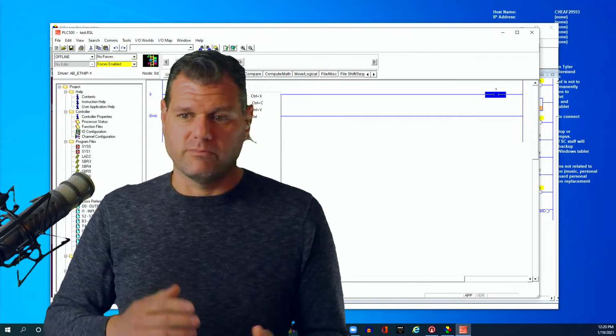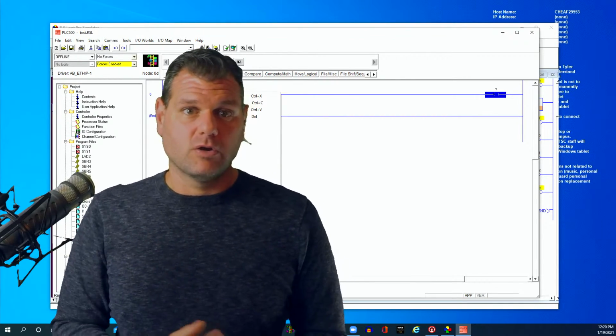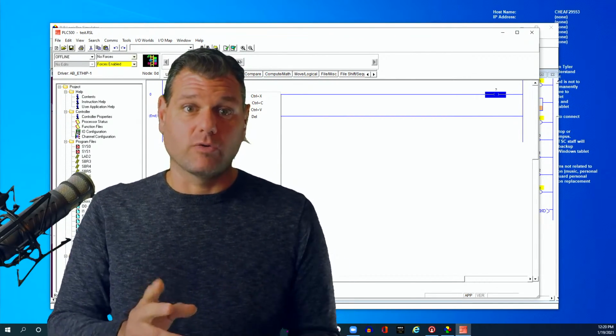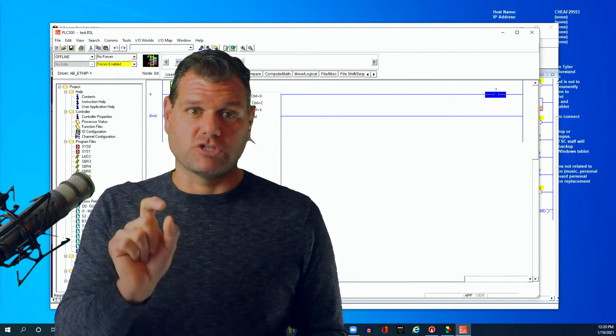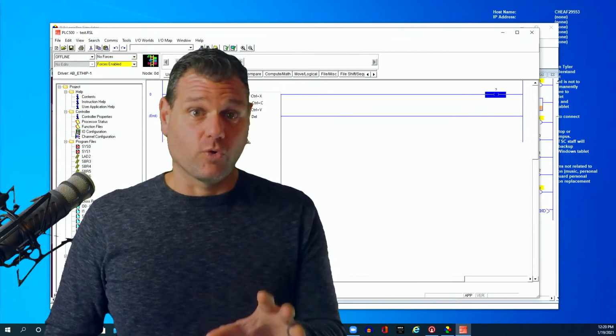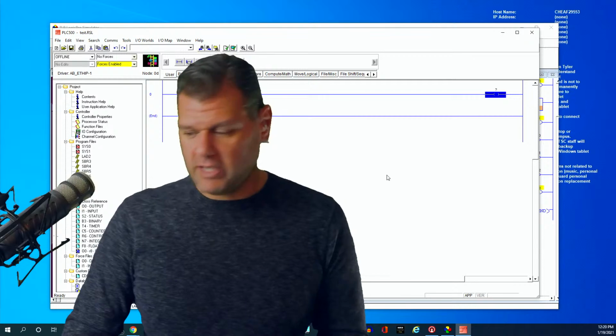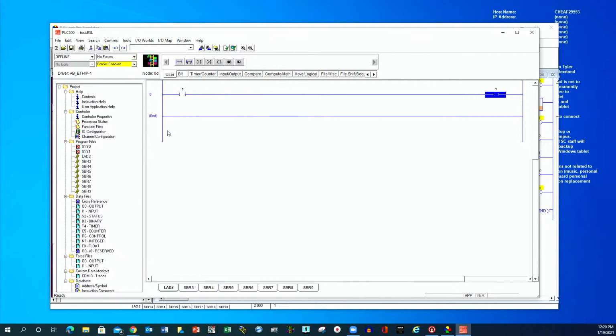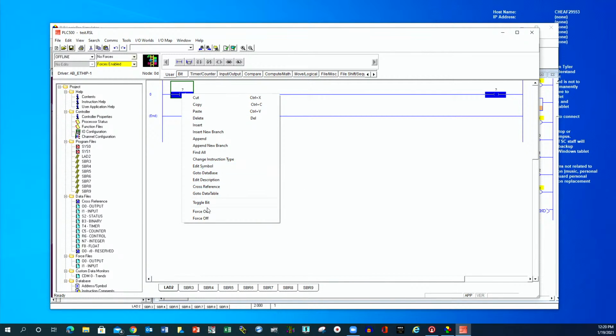So you can fake that someone pushed a button. But toggles only work momentarily. That's almost like someone pushing a button and stopping, whereas a force is forcing. You can force an input. It's not advised, but you could force an input on or off. That's also an option, if you wanted to say, okay, this switch is completely gone, I need to force it.